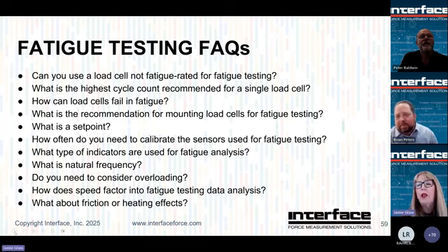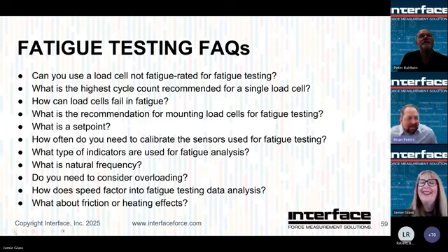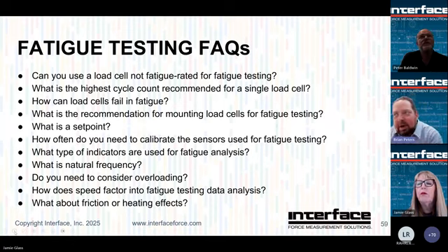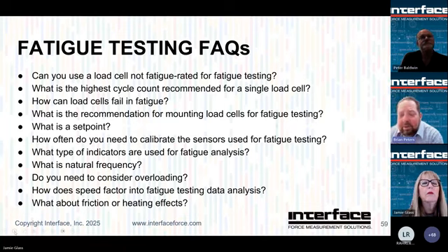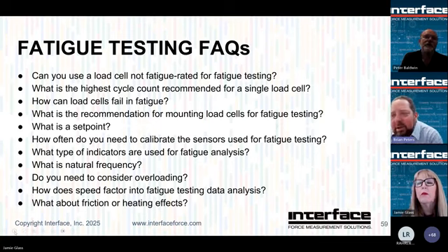We've got another one here. When tuning a PID loop for a test, sometimes the loop goes unstable. Is there anything other than going over the safe overload to be worried about as far as load cell damage, such as vibration, etc.? Okay. Yeah, that's a good question. So it sounds like it's kind of a runaway system, highly dynamic. First, I would be concerned: do you really have confidence in what the load cell was seeing, whether from a cycle count or from a force? We could be missing some of that from a data standpoint, like we talked about. So the load cell, your first concern is the right one. Did it see high overload? And again, that would potentially be an inertial overload. That would be the first concern.